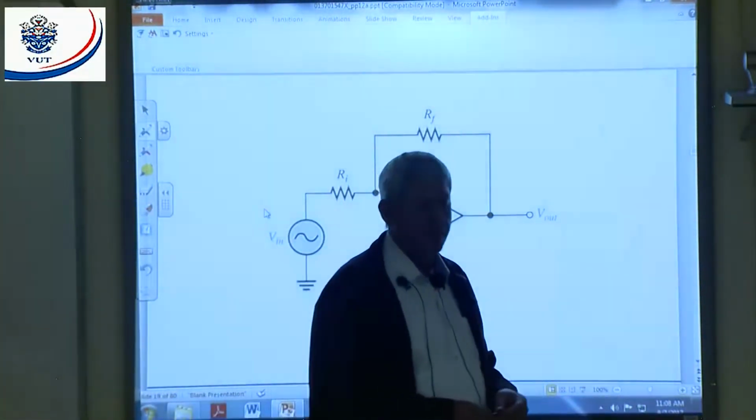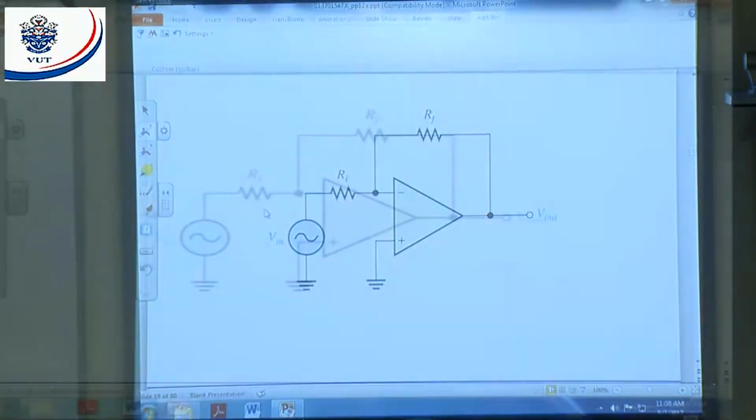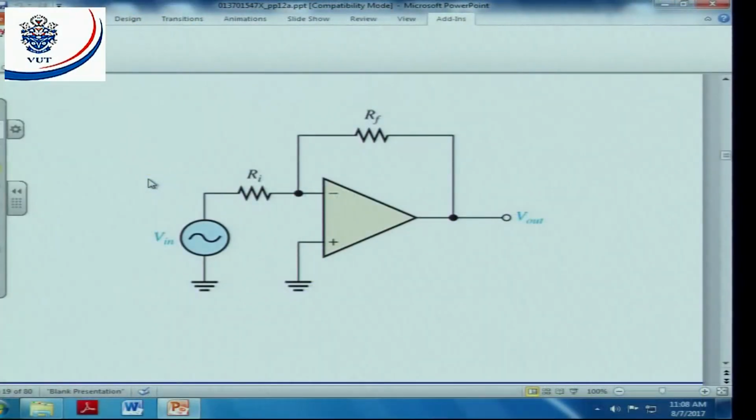Again, we're going to do it practical. I'm going to put in values, and we're going to do it quite practically, again with the DC source. Let's apply here an input of plus 10 volts. Positive there, negative there. Let's make R in 10 kilo ohm. Let's make RF 10 kilo ohm. Now, there are a few things I'm going to tell you that you should remember. Let's say without any input signal, the output should be 0.